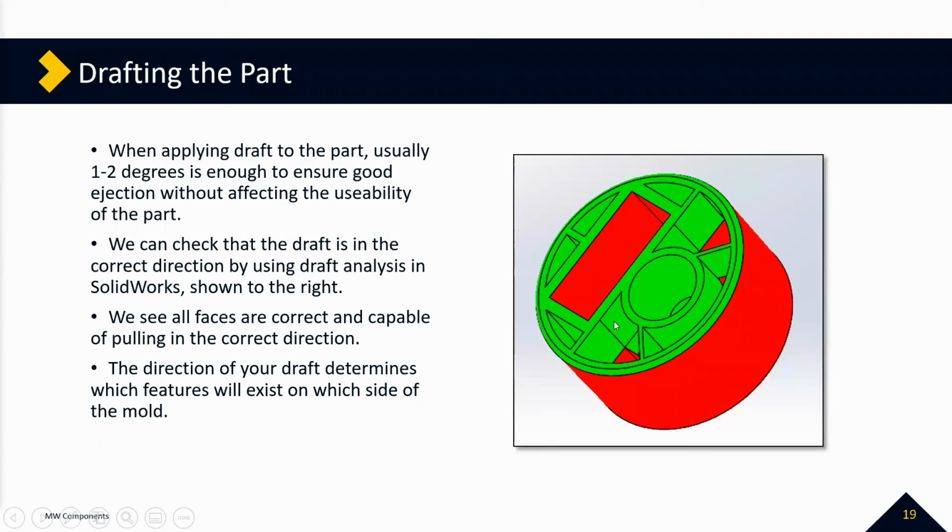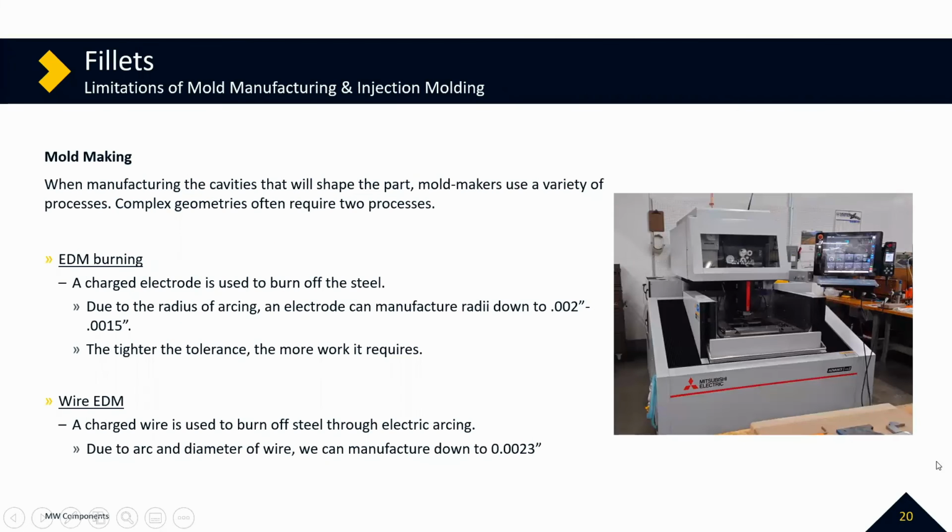And then all of this is being created and formed by steel on this side. So the parting line is actually internally somewhere down here in this section. The parting line is up here for this core. And then on the outside of the part, your parting line is right here. Continues.